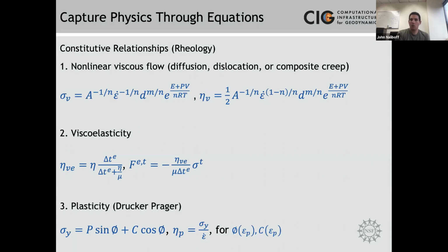In the material model we're going to use today, when we do a composite, we do a very simple averaging between these two values. This is actually not the ideal way to do this, and there's a different material model in Aspect which does a local iteration to figure out the proper stress, basically partitioning between diffusion and dislocation creep. At some point this year or next year, that's going to get ported over to the material model we're going to use today as well.